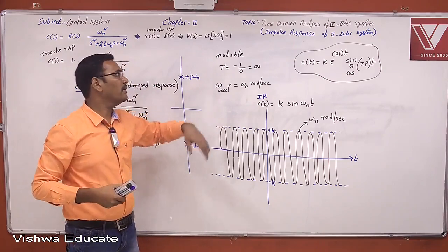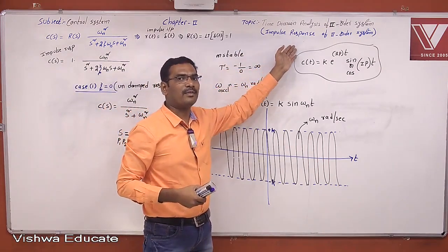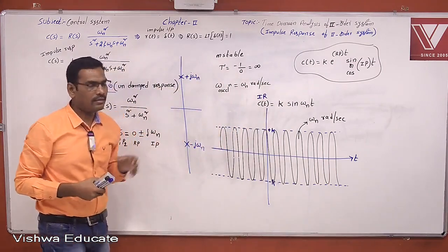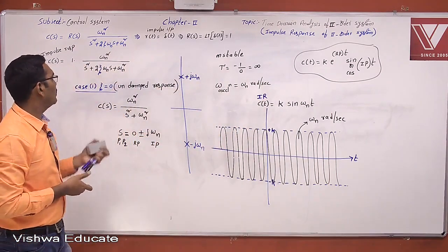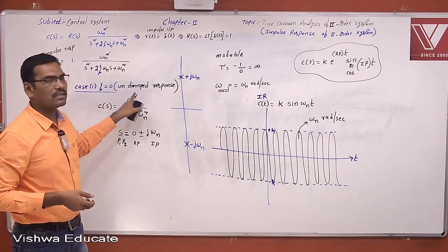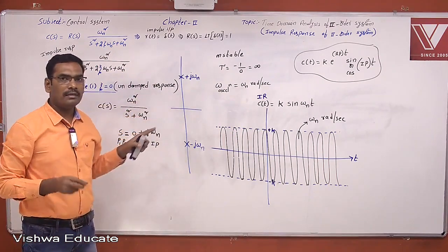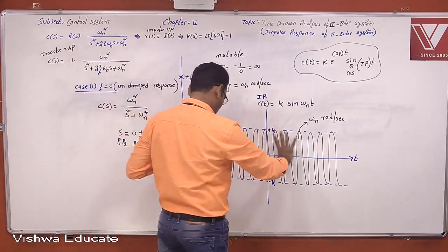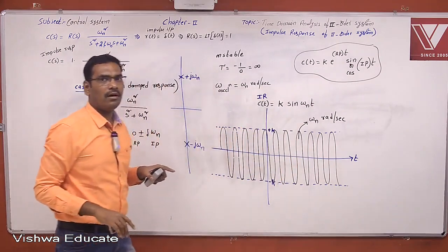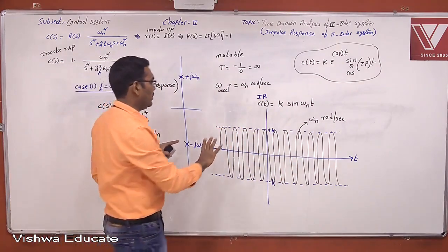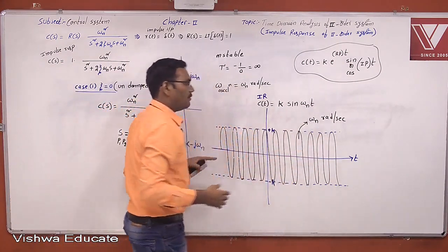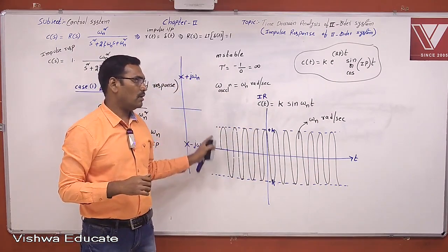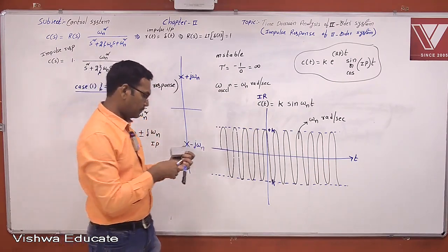This is the impulse response, the theoretical response. Again we will put a practical response, where we can eliminate all these delta values. Therefore when damping factor delta equals 0, this is called an undamped response, because we can put the name based on its response. The response maintains constant amplitude and frequency of oscillations. Understand? Therefore this response is called an undamped response.